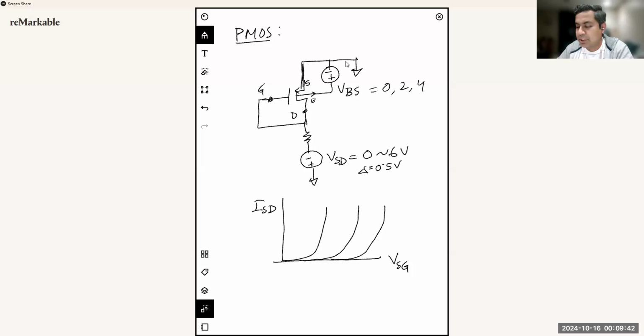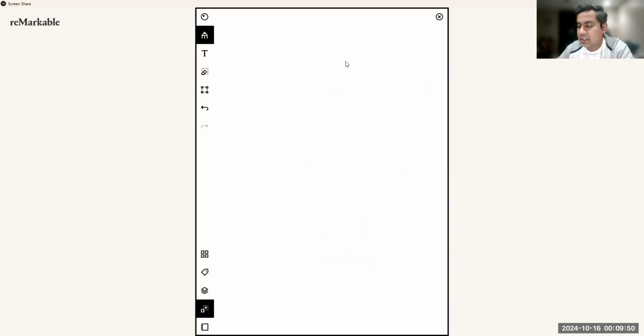In terms of simulation, you are going to use these circuits. You can simulate them in your LT-SPICE test bench. Build these circuits and then simulate them. You will need to add 3 library files that are already provided in the assignment page. Follow the instructions in the appendix of the handout that details what kind of library command or SPICE directive you need to include in your LT-SPICE test bench to run the simulation smoothly.